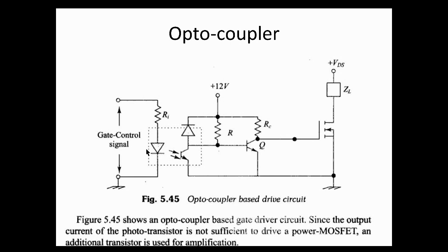You're also told what the voltage drop across this LED should be. So let's say typically you want a 0.7 volts drop across this LED, and this is 5 volts, then you can easily work out the value of the resistor that you need to put in series here so as to protect the LED.